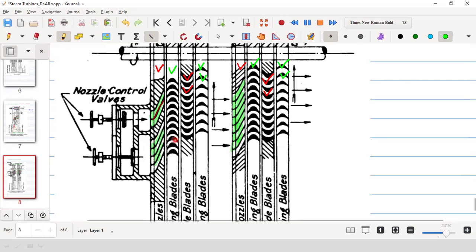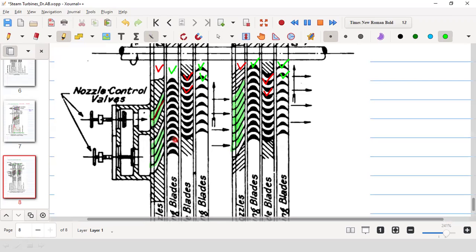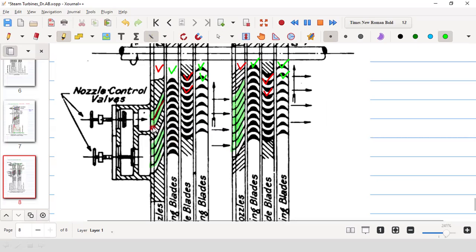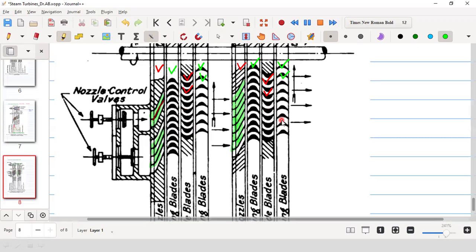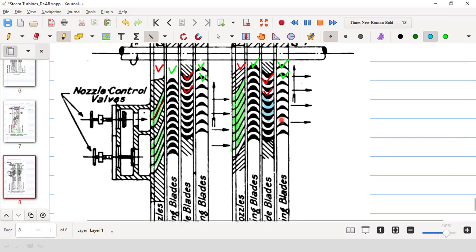So the nozzle will have a tangential direction because it has to create a velocity in the tangential direction. So the nozzle will be oriented along the tangential direction. But in case of guide blades, they are basically for impulse turbine. The guide blades are symmetrical. Guide blades are also symmetrical. So that is the difference. This red color, this is the guide blade, let me show with a different color. These are guide blades, this blue color.